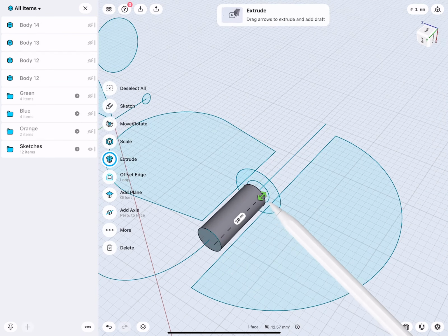So we can see that this is my original ring. So we made a mistake. This is actually good, but not this one. How do we fix this? Super easy. Select both faces, click on this, and then we offset this by 1 millimeter. But then you see it did it this way. Okay, so let's go back.